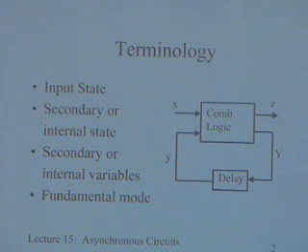This is again different. In case of synchronous sequential circuits, the changes could have been initiated just by a clock. A clock could take, for example, a counter through various states; you may not even have an enable count as an input, and still it will go through the states, and the clock will be responsible for doing that. But in case of asynchronous sequential circuits, all changes are initiated only by the change in inputs.